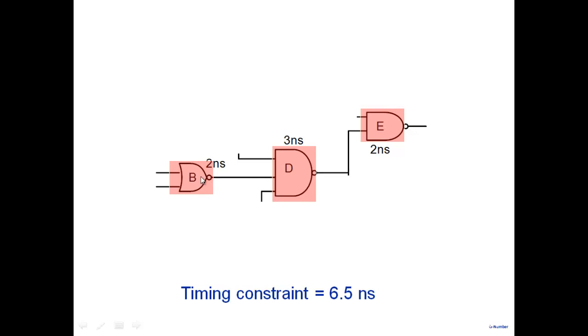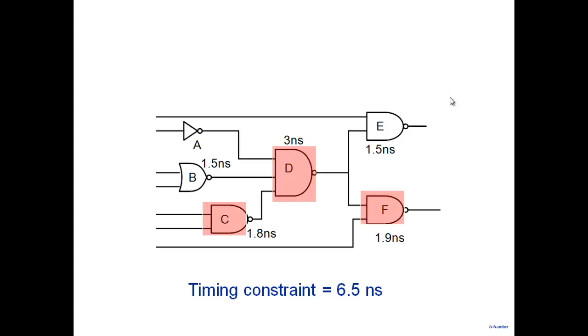So I may say, well, let me modify at the beginning. Let me intervene and modify to 1.5 nanoseconds. Again, I would see perhaps 6.5 nanoseconds. Again, I simulate. I modified it here, and the timing becomes 6.7 nanoseconds. So what is the message from all of this? The message is that the worst case path is not enough.